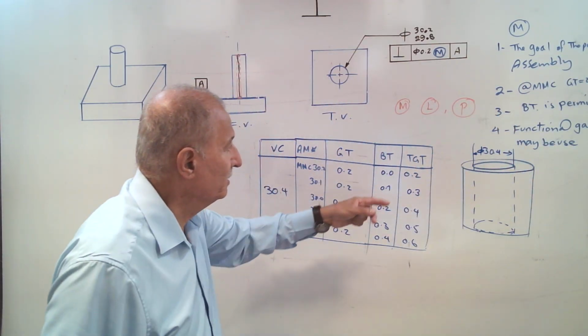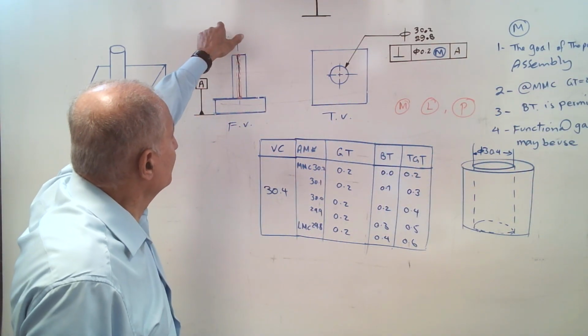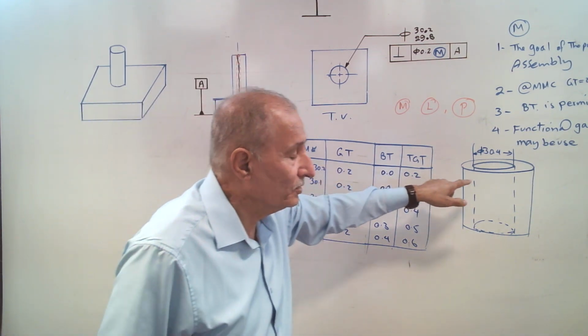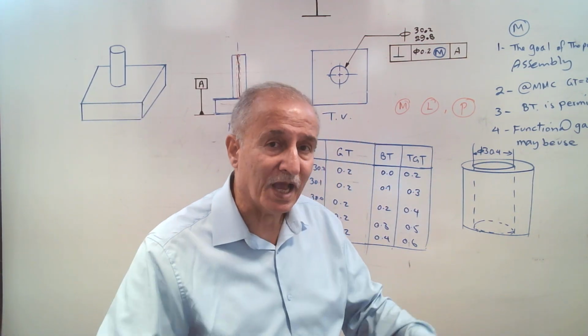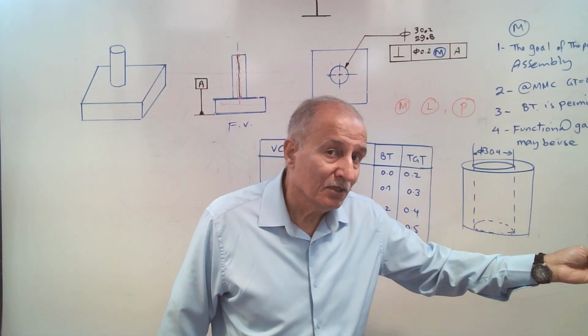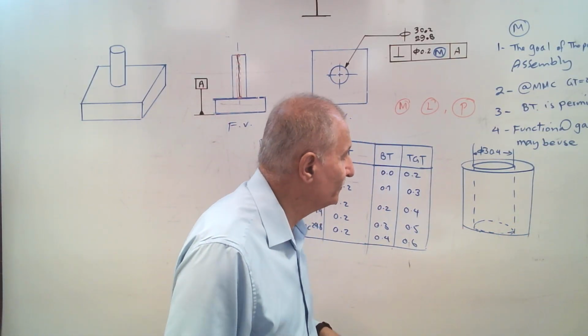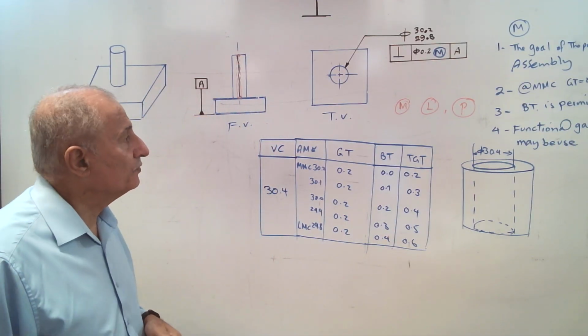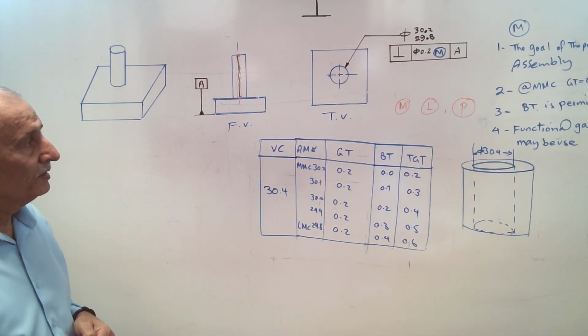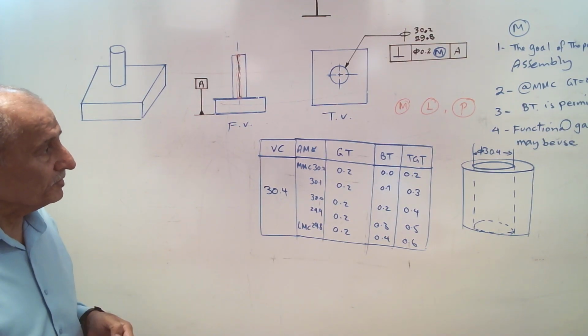And the part, if you put the ring here, it goes, go gauge, part will be accepted. Otherwise, it is opted for scrap or to rework, to fix it or correct it, if it is possible. That's for M modifier.